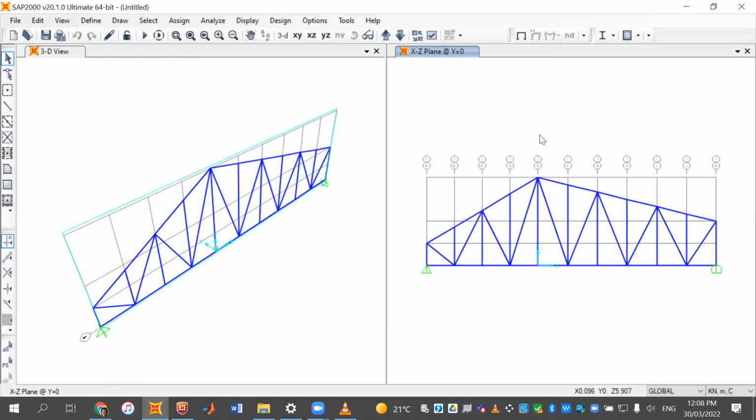Now what we need to do is, I told you in the report to draw 3 diagrams, which is your truss with the dead load. So you have 3 trusses with 3 loadings. One of them is for dead load, one of them is for live load, and one of them is for wind load.